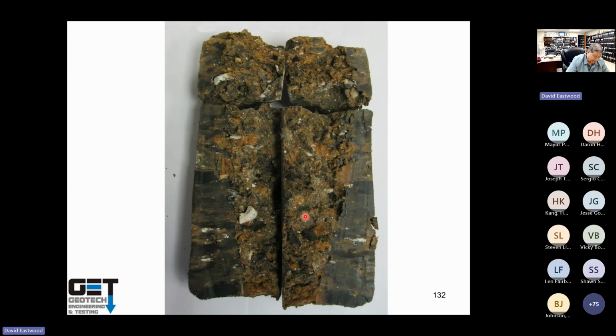Fill: on a lot of projects when you do mass grading, you want to put in a residential street. You're going to have a bunch of fill, depending on the site. You may have 3, 4, 5 feet of fill on your project. You can build your road on top of fill, provided it's properly compacted. You have to run density tests on your roadway at 50-foot spacing. Every lift, every 8 inches, has to be tested. You have to have density test results. And of course, the top 8 inches has to be stabilized. If your soil is fat clay, you stabilize with lime. If it's sandy or silty, you stabilize with lime, fly ash, or cement.